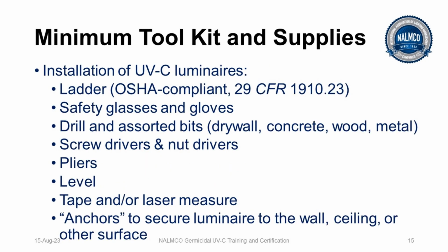Minimum toolkit and supplies. And this is just a starting point. You may have additional tools and whatnot, but you need a ladder that's OSHA compliant. You don't want to use one of these cheapo aluminum ladders that sort of wiggles when you open it up. We want an OSHA compliant ladder. Whenever I'm in the upper room space or near a UVC luminaire, I'll always wear glasses. If I'm going to have to touch the lamp or LED surface, then I would also wear gloves so I don't leave hand oil on the surfaces.